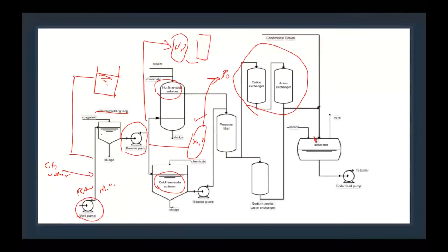Ultimately, we will make up to the deaerator, and the deaerator, with the application of steam, is going to vent out our non-condensable gases and send the water to the boiler feed pump. So that's a very, very crude and very limited overview compared to what we've actually looked at. We've looked at a lot more stuff than that.